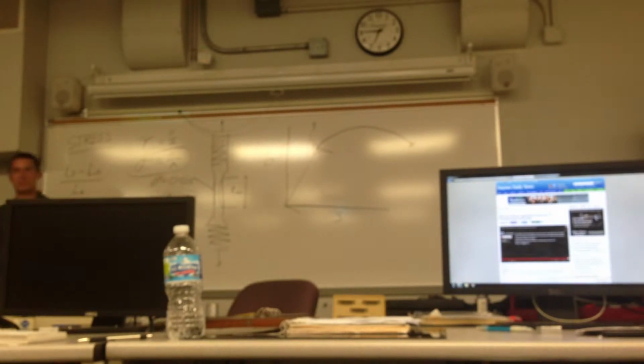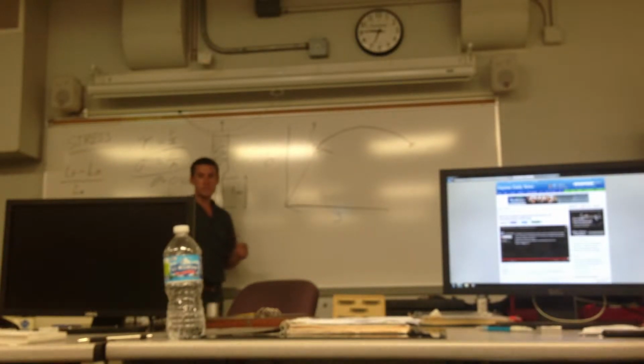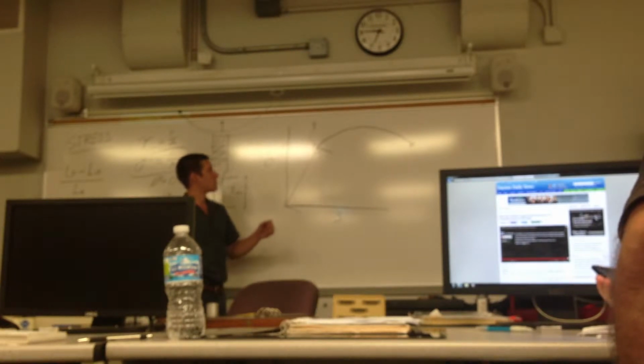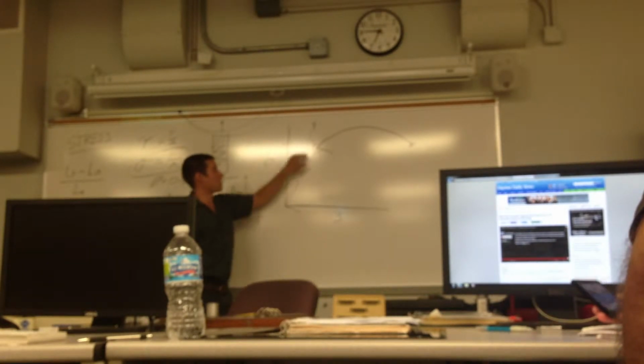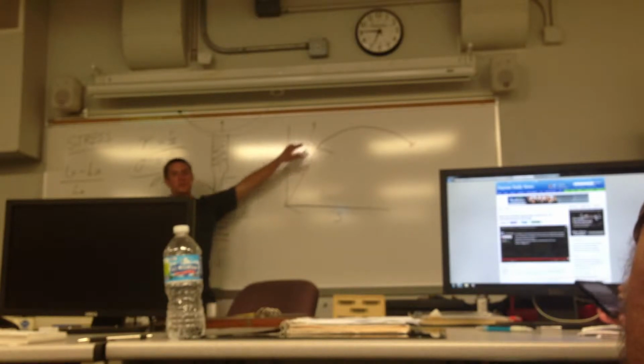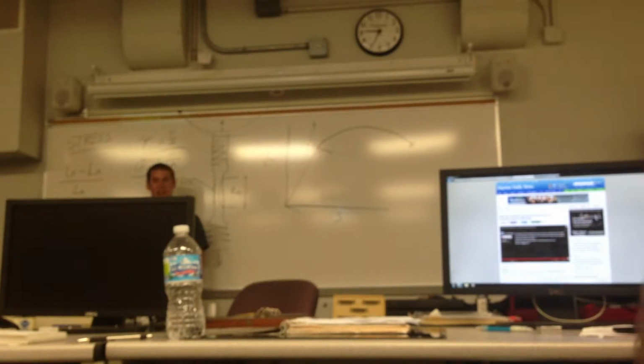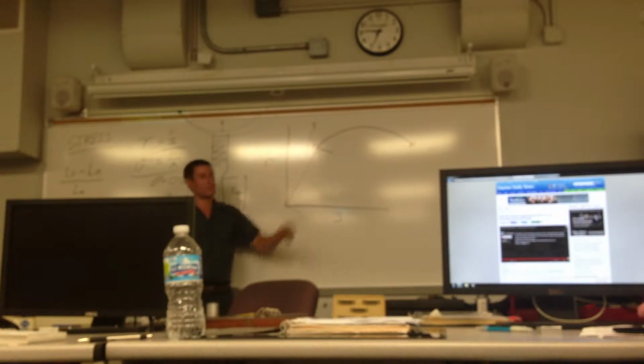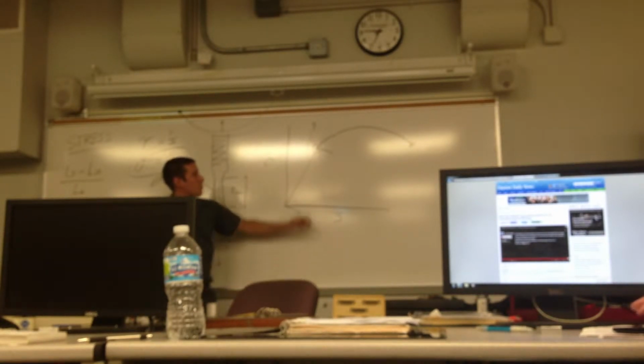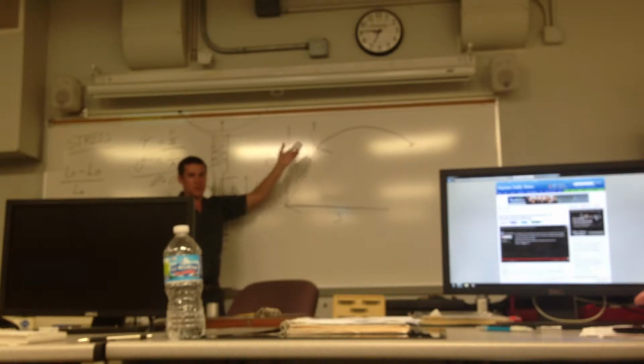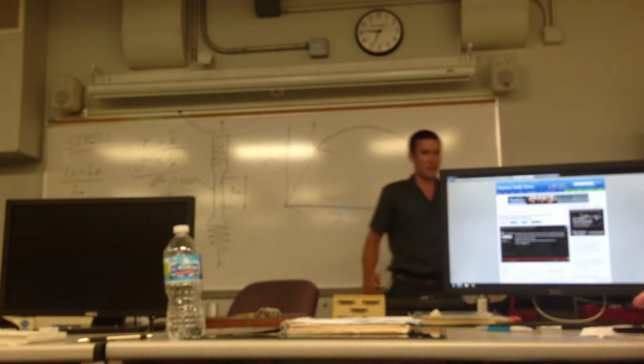It's irreparable damage. Right? You can always keep yielding it. Yeah, you can. Anywhere in between there is where it can be yielded, but once you hit that X, it's broken. No, you only yield it once you hit there. You don't ever want to yield a material, usually. You don't design things like, oh, if this tank drives across this bridge, it's going to yield the bridge, right? No, probably not a good idea. You probably want to stay in this elastic region. You don't really want to ever yield material on purpose. It's usually not a good thing.